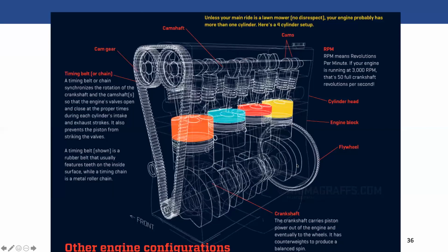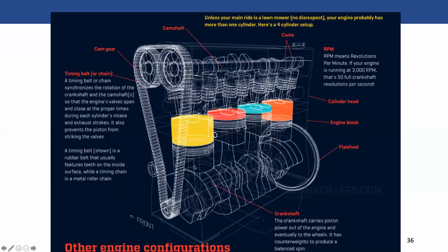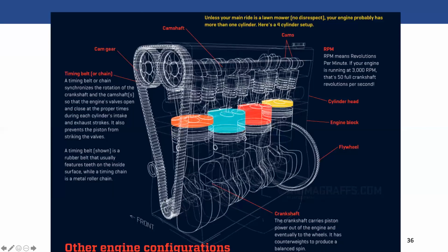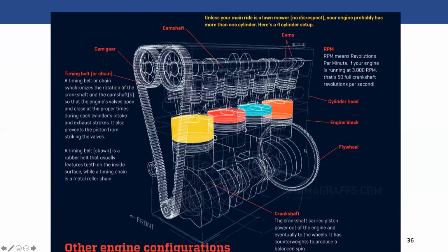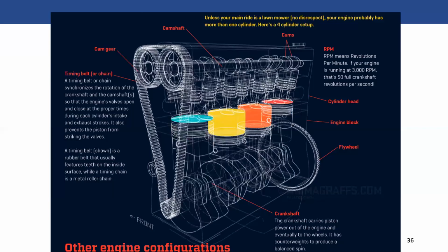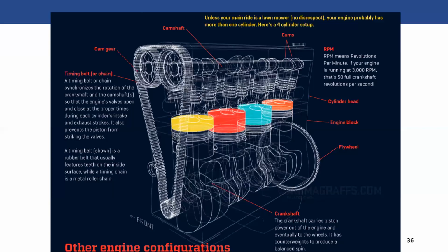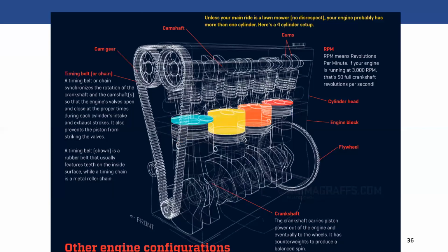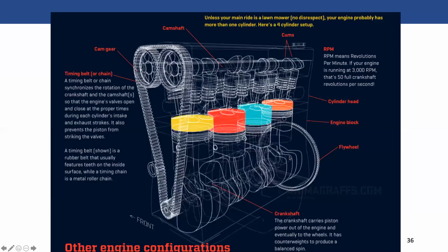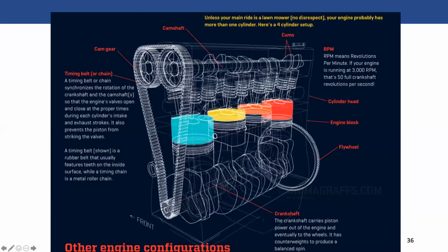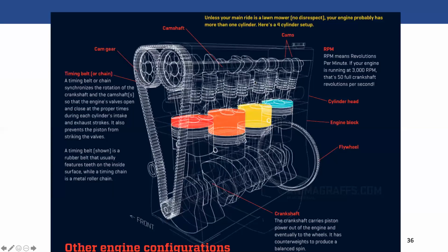Okay, so what's actually going on here? As the pistons move up and down, they are rotating this thing on the bottom called a crankshaft. You might be wondering from the last slide, how can I so accurately time when I'm opening the valves, when the fuel is getting injected, and when the spark plugs are happening? It's actually all in a mechanical timer. As the crankshaft rotates, it's moving this belt, which moves this thing up at the top called a camshaft.